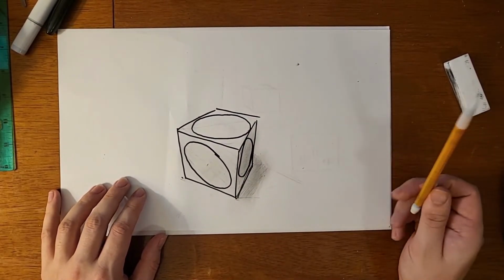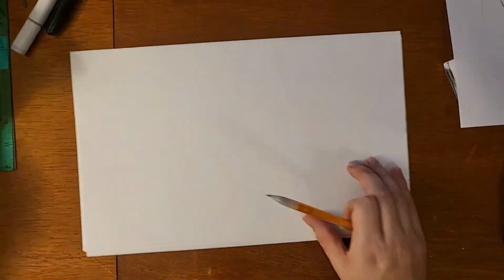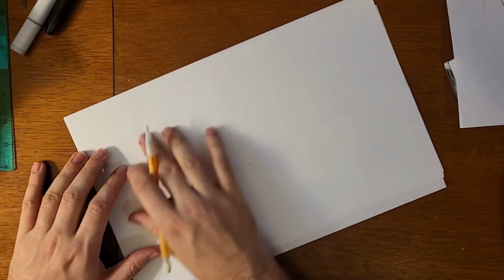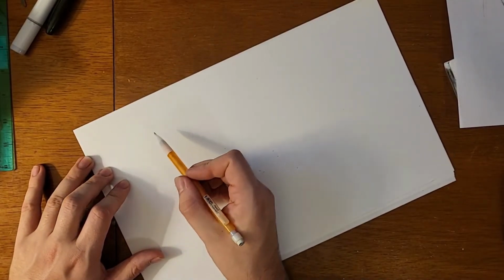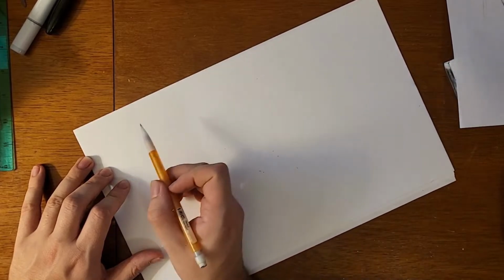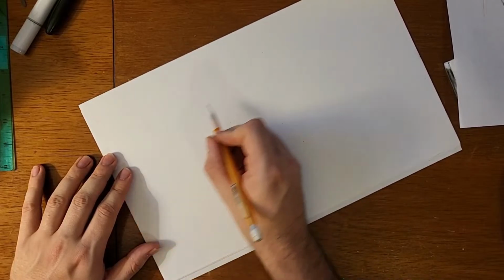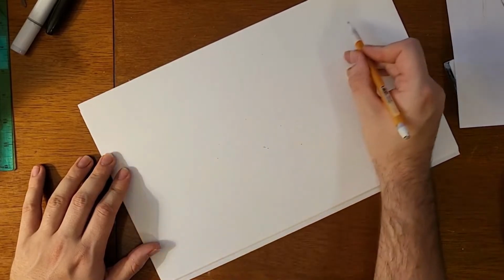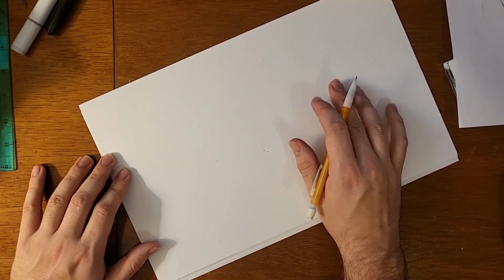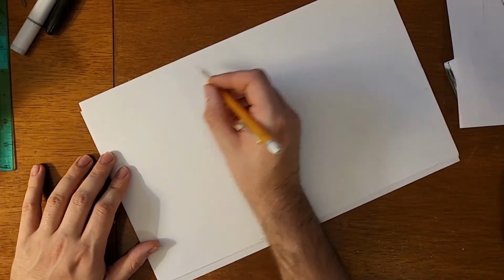And as for drawing the lines, I spent a lot of that time, I can use this one, just going paper at an angle, pencil in my hand, drawing a line. Now, techniques for drawing a line, you want to use your elbow, not your wrist. You can use the wrist for really up close, but when you've got a nice big piece of paper, that's when you can start moving your elbow instead.